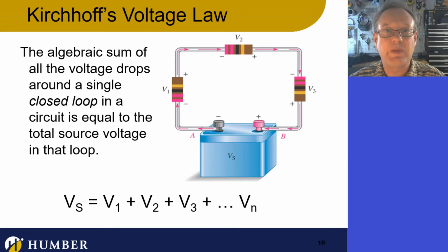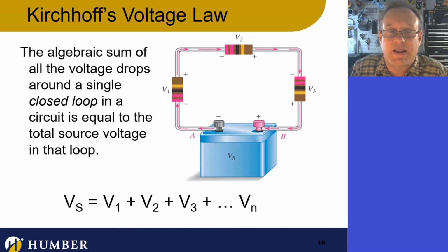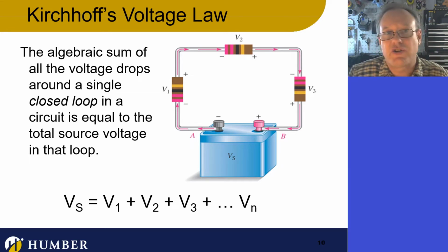So for now, just believe me here, we have this concept called voltage drop. Essentially, it's the energy that's lost, because we know voltage is energy per charge, right? It's the energy that's lost pushing that charge through a particular resistor. So we can look at Kirchhoff's voltage law like this. The total energy supply coming from the battery that pushes that charge or those electrons through the circuit is lost by the time it gets to the end. Actually, that's per coulomb though, right?